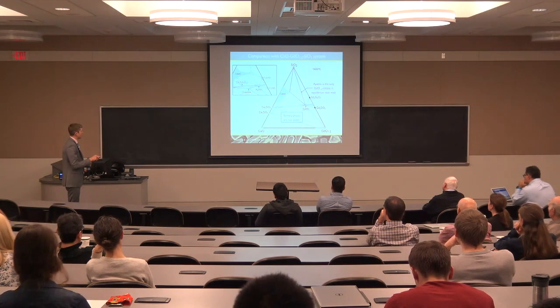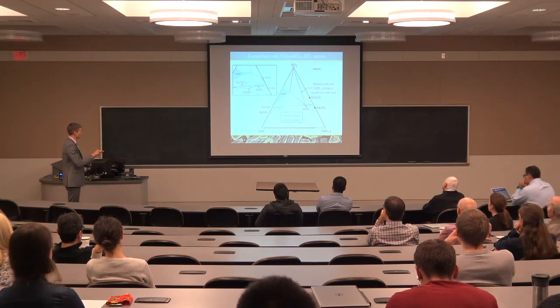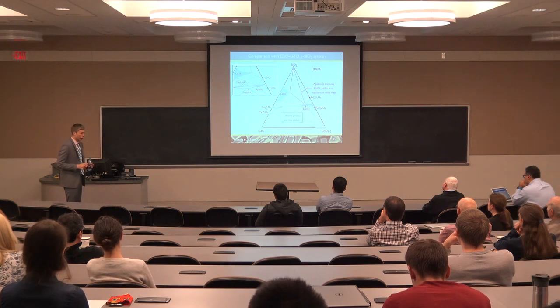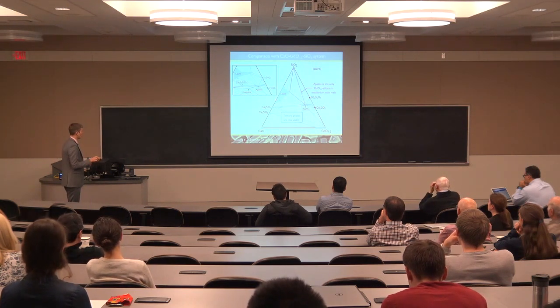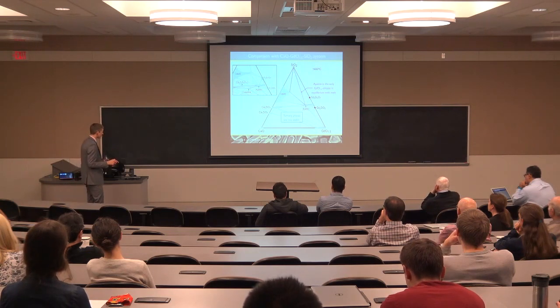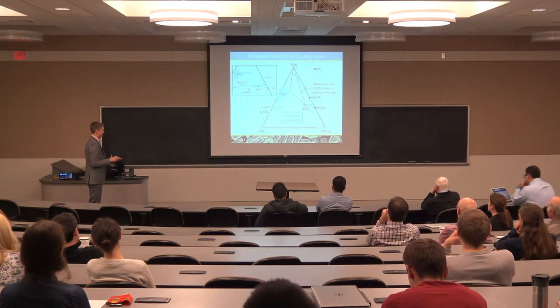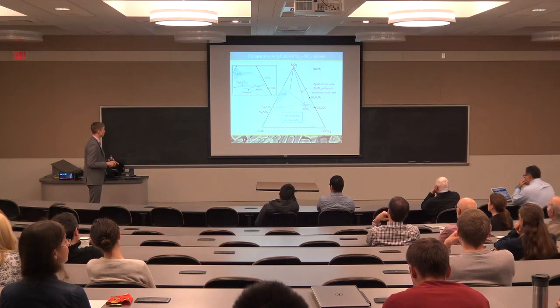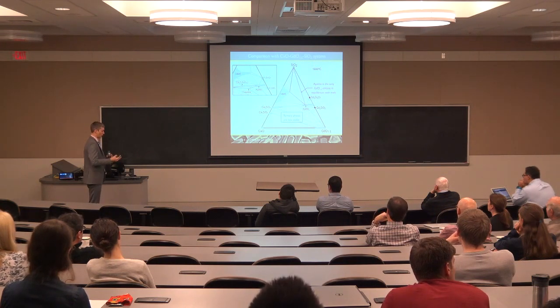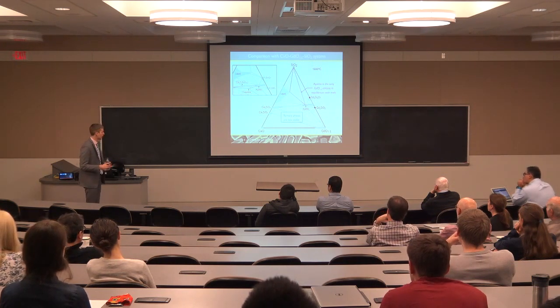And we also find that for the most part, unless we're basically crystallizing out calcium silicate or pure silica, any interaction of any gadolinium-based coating material with a calcium silicate liquid is going to produce apatite. And that means that from the perspective of designing coatings that we don't want to interact with the liquid, we should pick yttria instead of the gadolinium, because the yttria is more likely to eventually get to a point that the reaction stops.